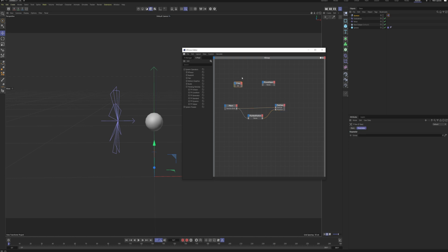So up in P Pass, I'm just gonna connect these two, and inside of the P Pass we need a particle group, and we can just go to custom, TP settings, thinking particles, and we'll just pull in this all particle group here. And then I'm gonna go to my P Surface Position, and I'm gonna choose my sphere as my particle position.